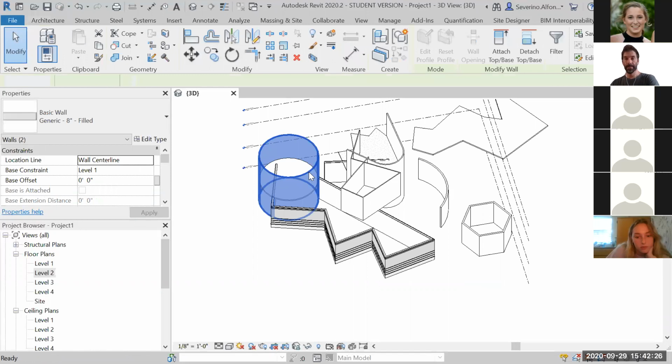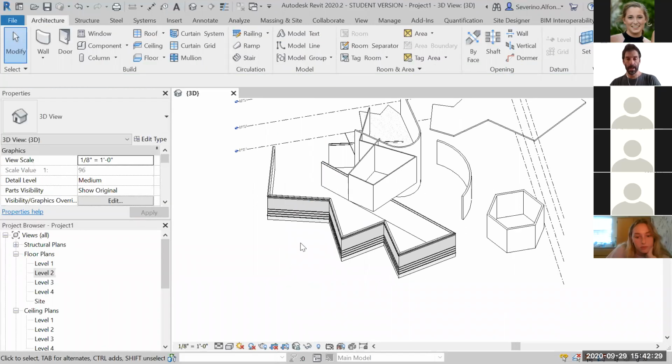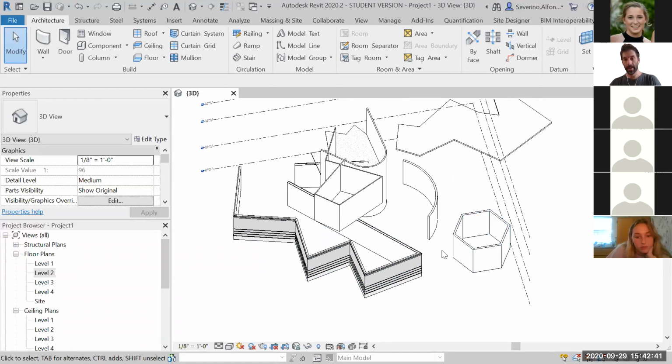Let's imagine, I'm gonna delete these things, that you have this chain of walls, which is like a polyline setting of walls. They have to be connected. When you have multiple walls connected to each other, there's a way of selecting the entire chain at once. The way to do that is to step on top of the first wall. It turns blue without selecting anything, pressing Tab once and lifting the button, and then clicking the mouse left button once.